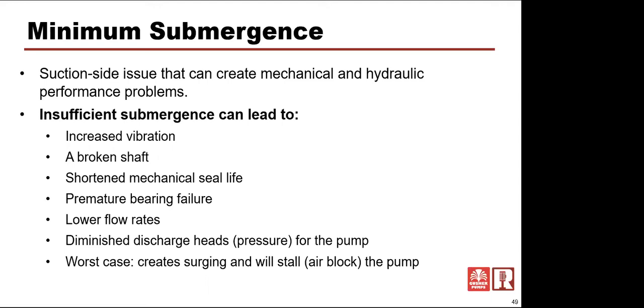If you get enough air into a pump, you can create a condition where the pump loses prime. So if we're drawing from a horizontal tank, or a horizontal pump drawing from a tank, if that liquid level gets low enough, it'll get enough air into it to lose prime, even though the liquid level may be above that pump still. Same type of scenario that happens inside your bathtub as the liquid level gets low enough.